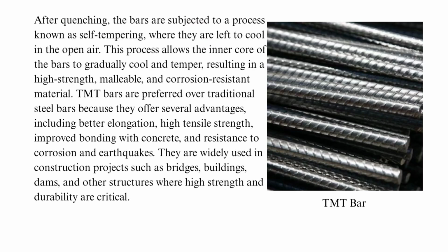After quenching, the bars are subjected to a process known as self-tempering, where they are left to cool in the open air. This process allows the inner core of the bars to gradually cool and temper, resulting in a high strength, malleable and corrosion resistant material.